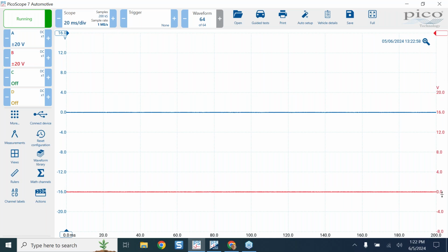Again, everybody starts a scope differently. I do always recommend, though, if you're not going to use all 4 channels, don't turn them on. Keep the channels off when you're not using them, because it obviously reduces your sample rate and the memory for the scope. The more you have open and turned on, the more it reduces. The scope doesn't know whether it's hooked to anything or not. So only have the ones open that you're using.